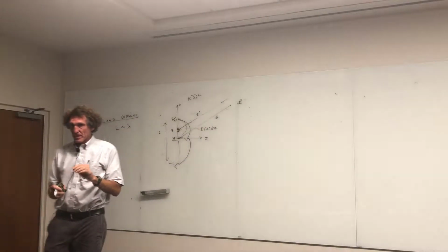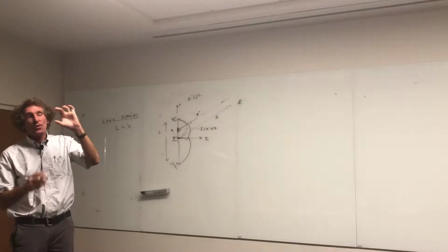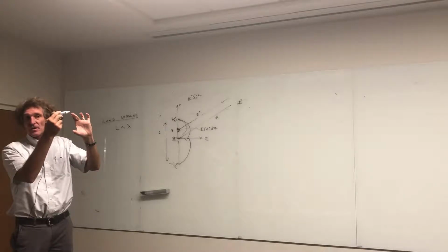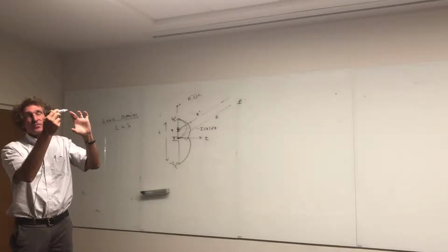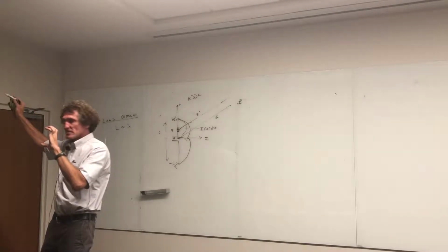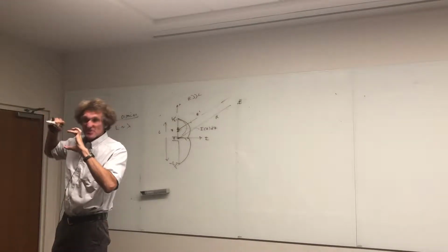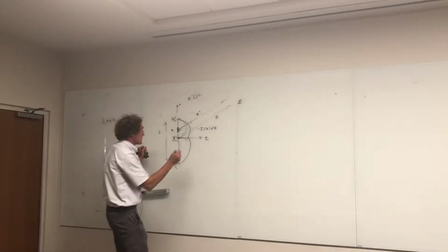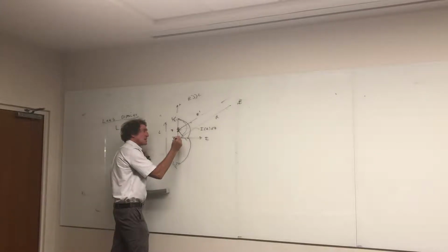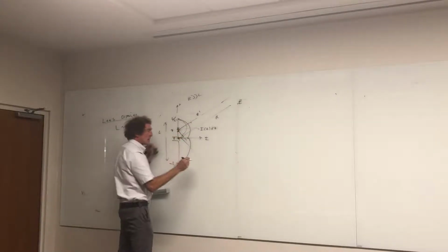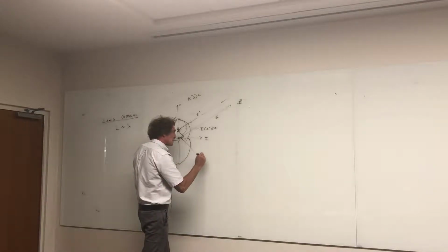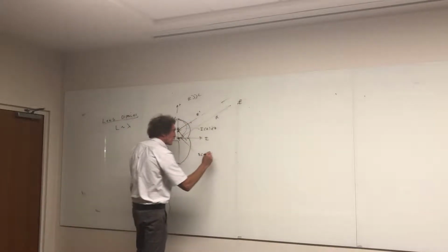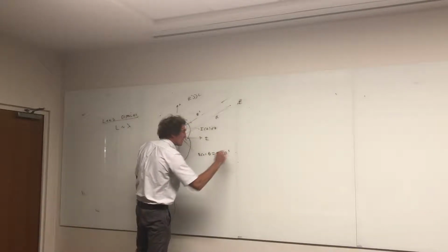Think about this. If I have something spaced this far away, where really this is the center of my antenna, here's where my chunk of current is that I'm talking about the differential actual electric field from. If I go from here to the center, and I look at the difference in radius vectors, they're the same length, they're about parallel, follow me? The difference in length can be gotten this way. If I look at this, I can say this difference in length, if these are parallel rays, would just be equal to Z times cosine of theta. That would be the difference in length from R prime. This would be really R minus R prime. Can you all appreciate that, class?